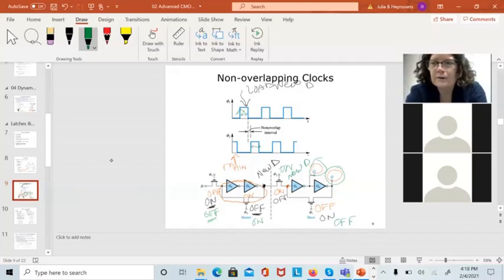This first pulse here is going to control something called the setup time, T setup. While phi 1 is true, which is going to equal our setup time, I have to maintain D stable. Because if D is not stable and it changes during that time, I'm going to get a different value loaded in. So during this whole time, D has to stay stable.